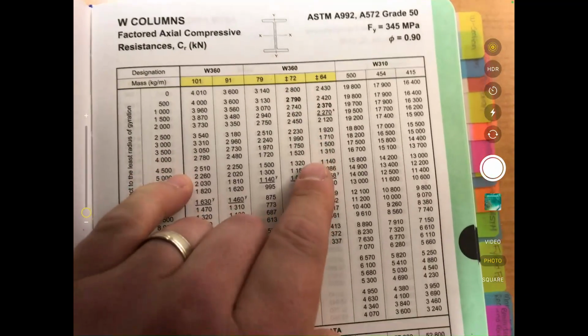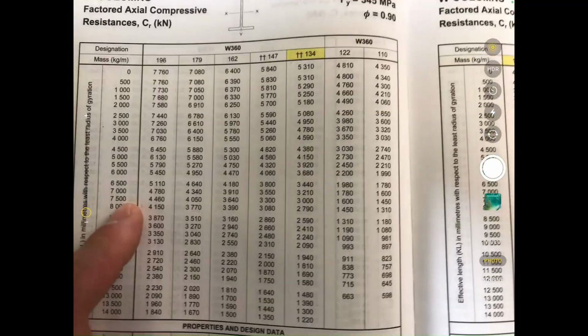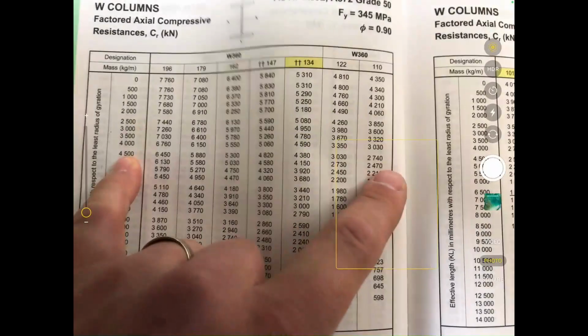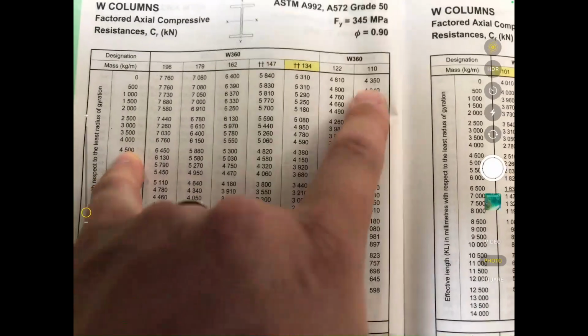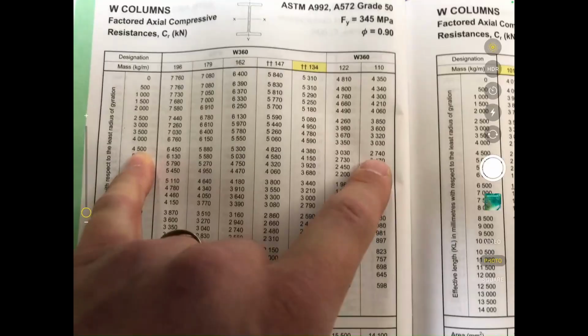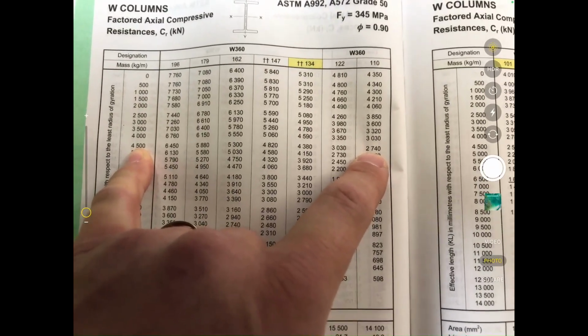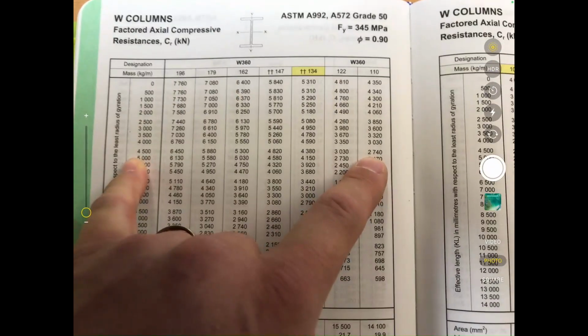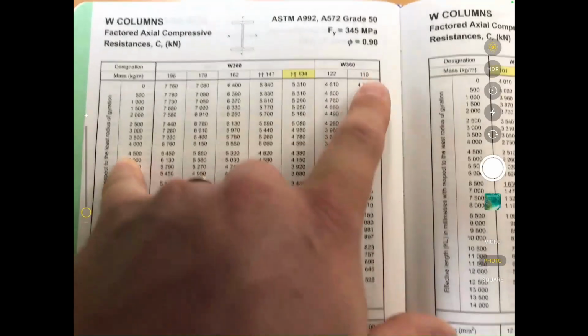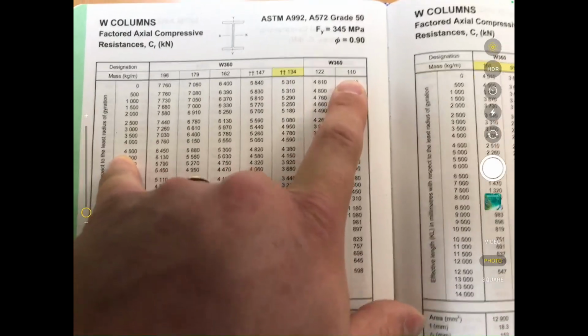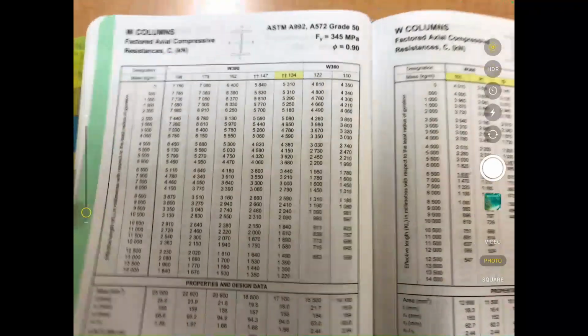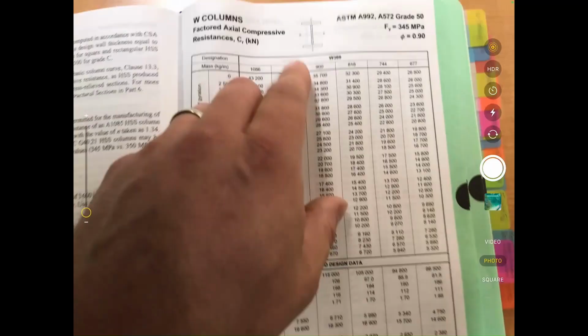Let's see. Well, there's none of them here. If we go to the next page, 4500, a W360 by 110 has a strength of 2,740. That's a little bit less than the W310 by 97, and it's a little bit heavier. So that doesn't sound like a good deal to me. What else is here? Nothing. Just heavier 360s, right, going all the way up to